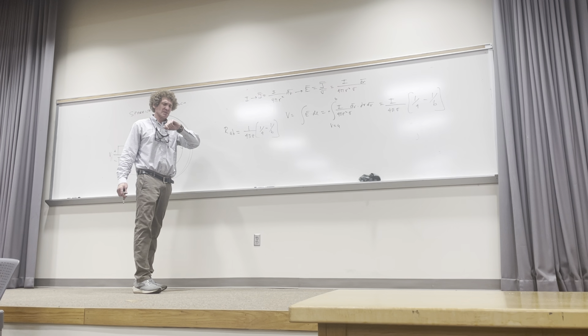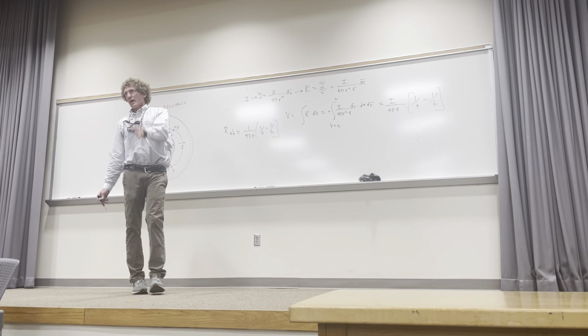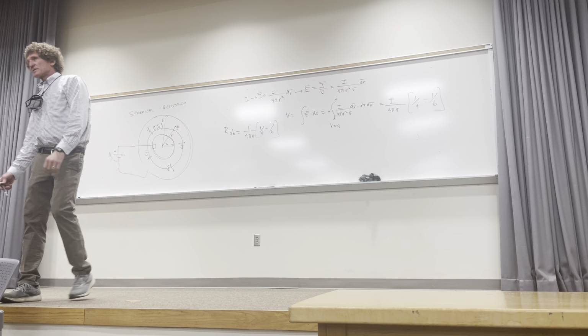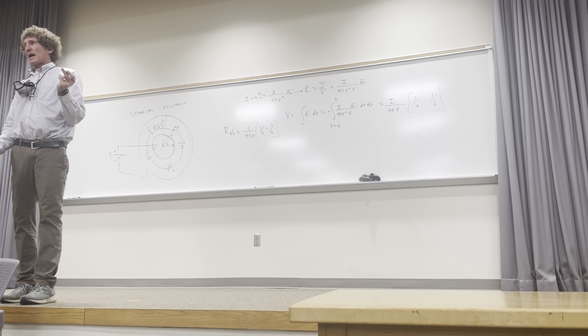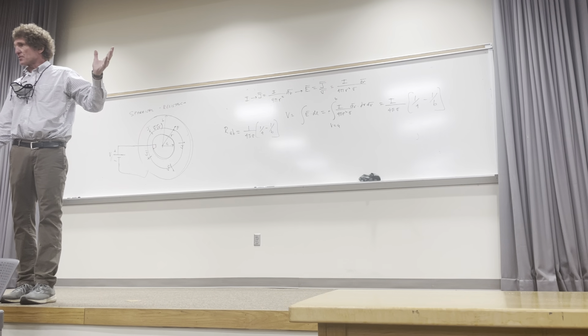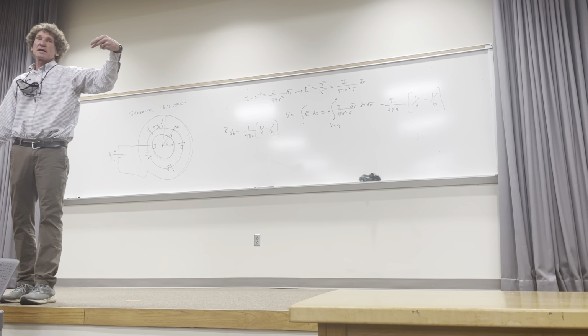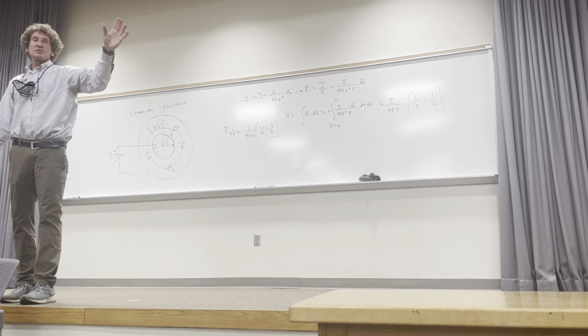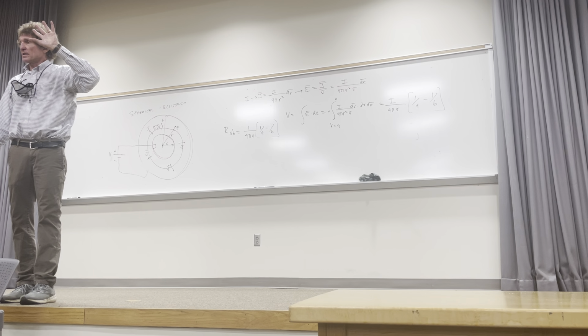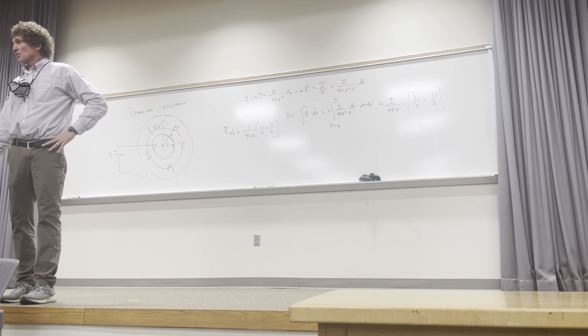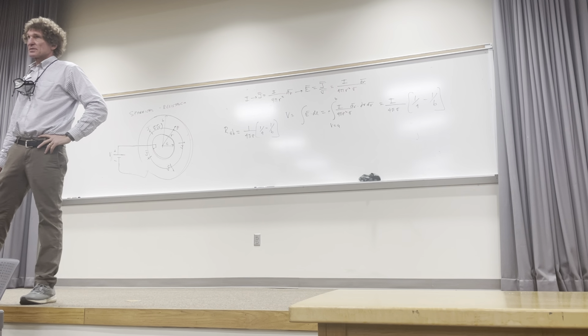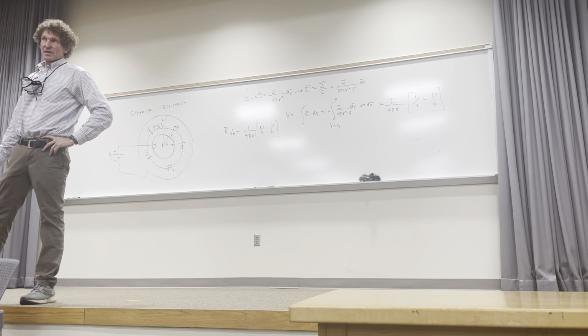Last thing I'm going to mention, is it over? It is. I didn't get to do several examples here, but when we get into capacitance, it's going to be the same methodology. We assume something, usually charge, then we get the E field, then we get the voltage, and then we know that, remember, capacitance is what? I mean, really, charge is voltage times C, right? So if we assume charge, get voltage, we take charge over voltage, and we get capacitance. It's the same method. I'll show you some tricks to that on Wednesday.